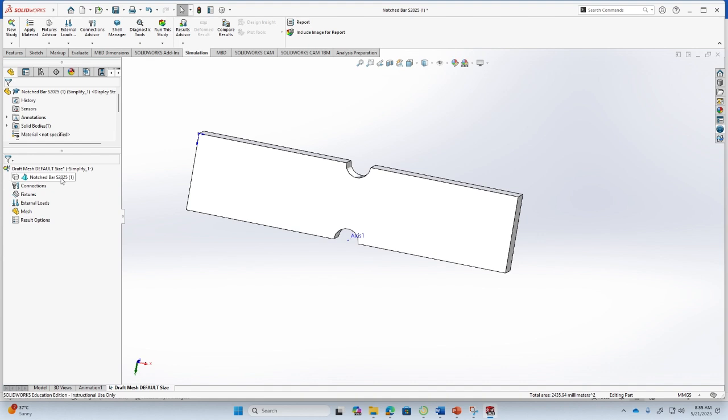The second step is to tell the software about material, okay? Because if you don't tell it, it will not know whether it is steel or it is plastic or whatever it is, okay? So you have to define the material. The third step will be to assign what we call the boundary and loading conditions, okay? And then after that, you will have to do what we call meshing or discretization. And then finally, you will submit it for solution and it will produce results.